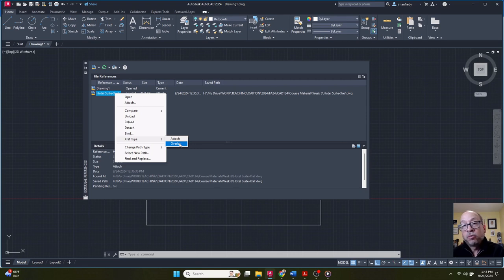You might bring an architectural file over, but the architect's drawings might include plumbing, mechanical, electrical, structural information, and those other XREFs might be useful to you or not. So in case they're not useful, do an overlay. The XREF of the AutoCAD comes in from the architect, and the other files do not come over. Otherwise, attach, you see all of them.